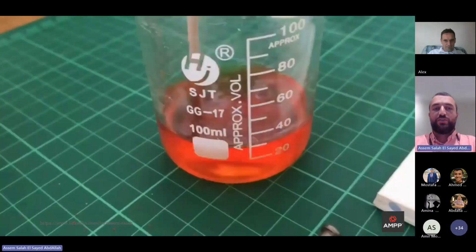And we have now a small video which explains the idea. Here you have two samples. One sample is a steel anchor connected to a zinc plate, and on the other hand we have a steel anchor only, or steel bolt only. And in this experiment, you will add some HCl, a very strong acid, which is used to corrode the steel metal. And as you can see, on the right hand you have a reaction between the bolt and the acid, and on the left hand, the steel bolt is still there, and the zinc sacrificed itself to protect the steel.